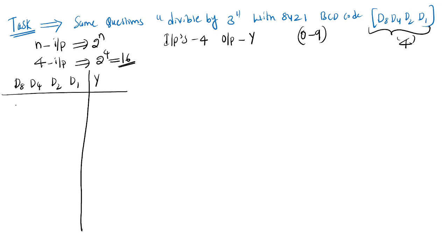So you write 0 0 0 0 and so on. We only consider the BCD range, which is represented as 0 to 9 only. When we discuss a BCD adder, there I will tell you. Suppose 1 2 in BCD, we need to declare separately 0 0 0 1 and 0 0 1 0.